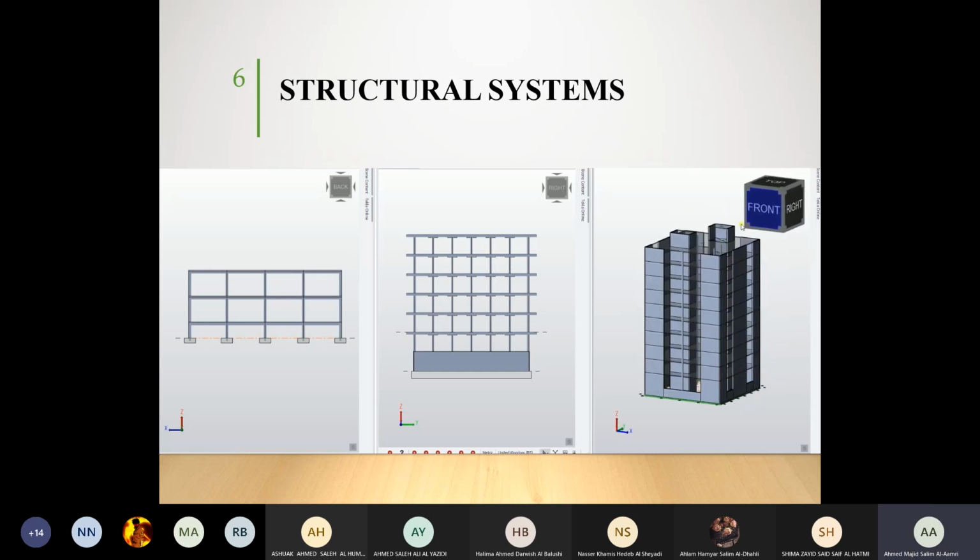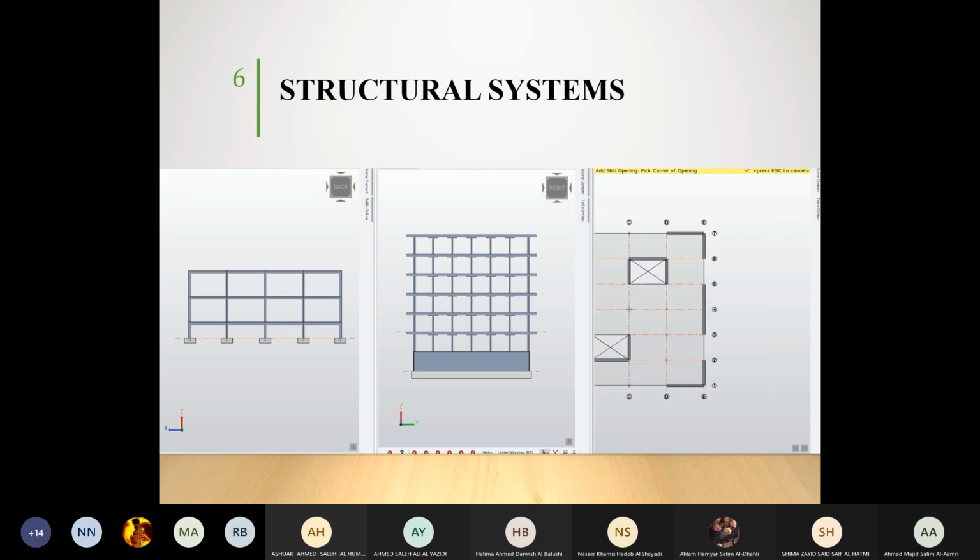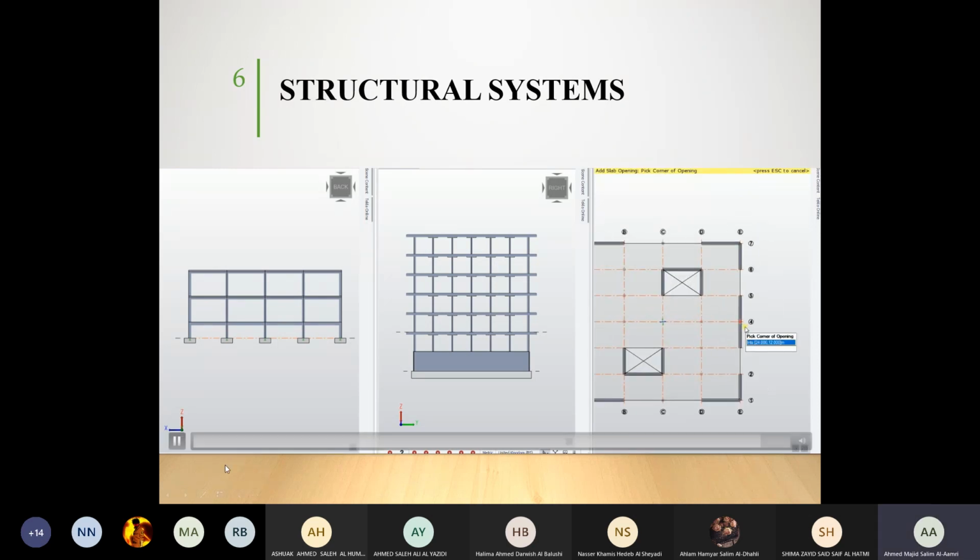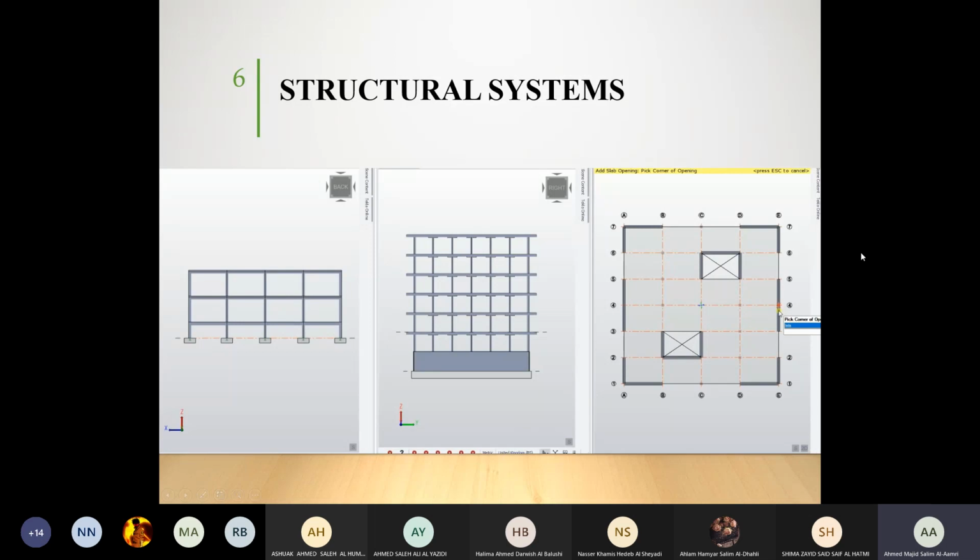So now if you want to see a plan, this is a plan of your structural slab layout. Here we have core walls. So this is a core. This is a core because it's a combination of 2 walls. Core. This is a core. This is a lift, which is representing a core wall. Now this is one wall. This is one wall. So these are acting as shear walls. And this X is representing an opening. Whenever you are having a lift, of course, there will not be a slab, except if you are talking about the roof slab.